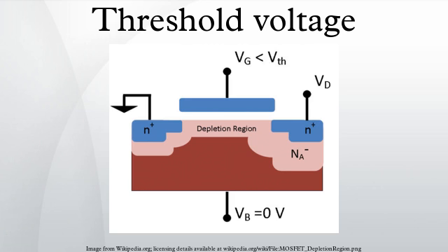When referring to a junction field effect transistor, the threshold voltage is often called pinch-off voltage instead. This is somewhat confusing since pinch-off applied to insulated gate field effect transistors refers to the channel pinching that leads to current saturation behavior under high source-drain bias, even though the current is never off. Unlike pinch-off, the term threshold voltage is unambiguous and refers to the same concept in any field effect transistor.